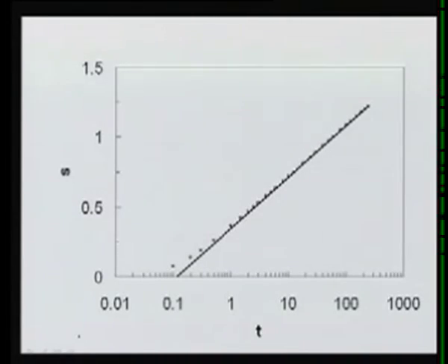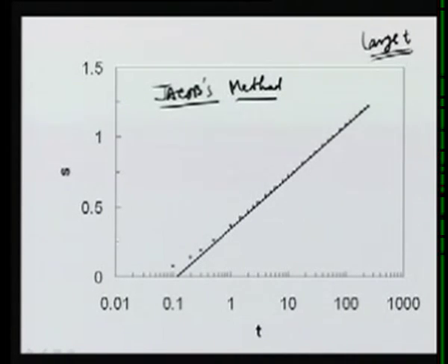One of the methods which we have seen is known as the Jacobs method, or Cooper-Jacob method, in which we say that for very large value of time, so large t, the well function can be approximated by the first two terms, and then what we do is we fit on a log plot, we fit a straight line through the data corresponding to large time and extend that straight line up to the 0 point, the drawdown equal to 0 point, and we call this t0.